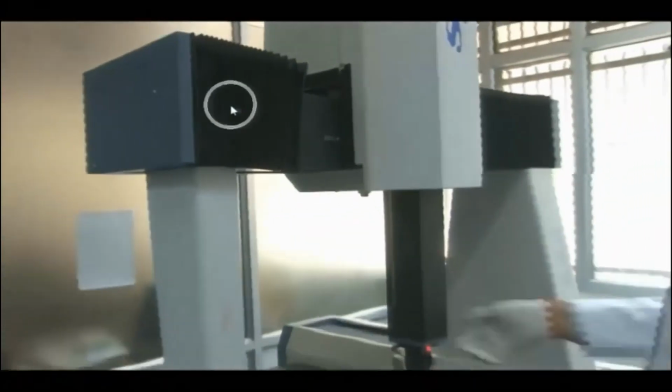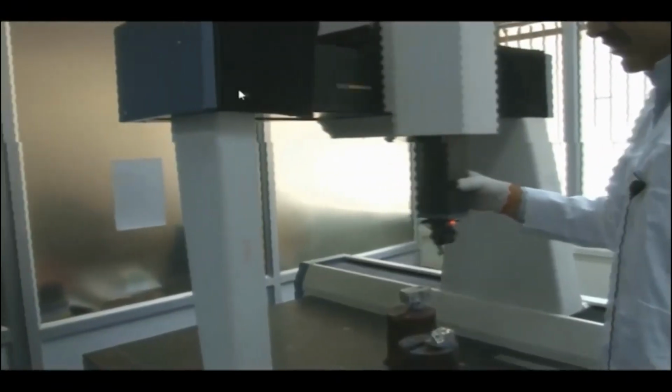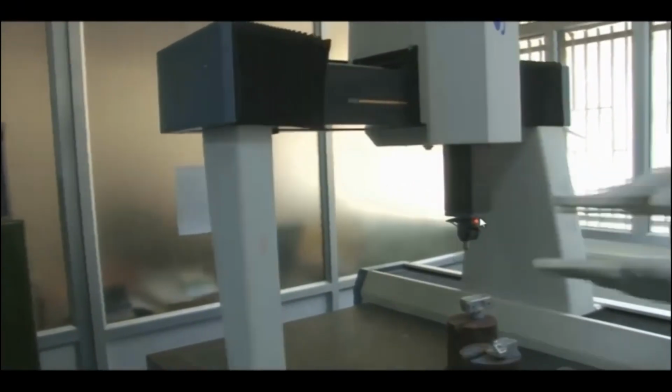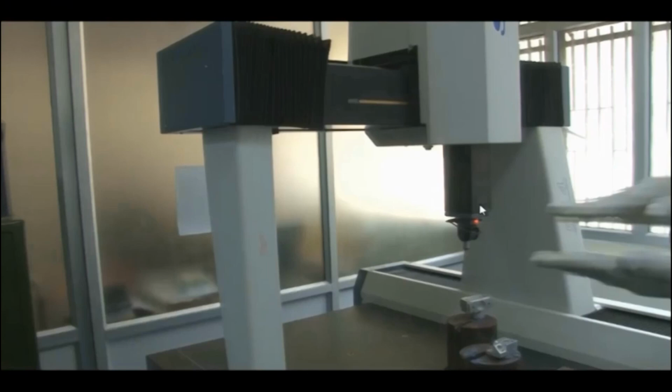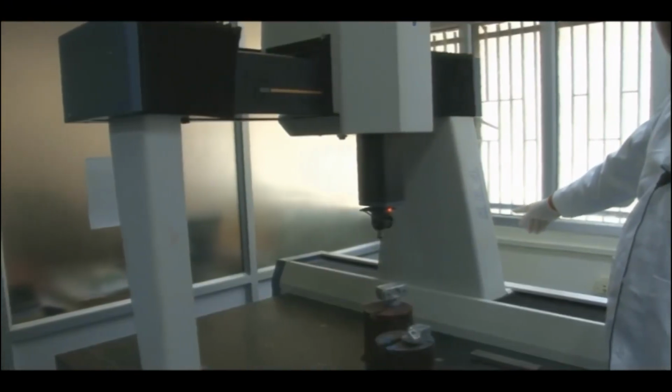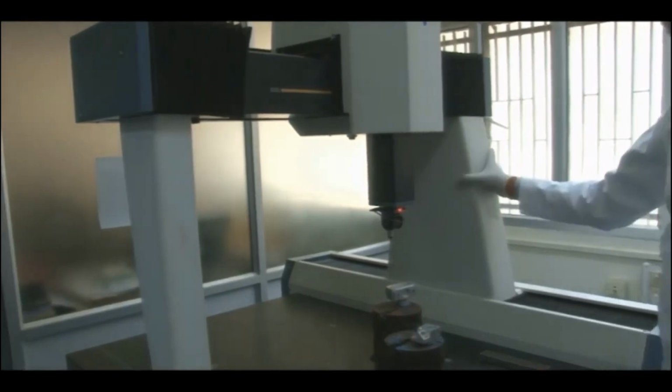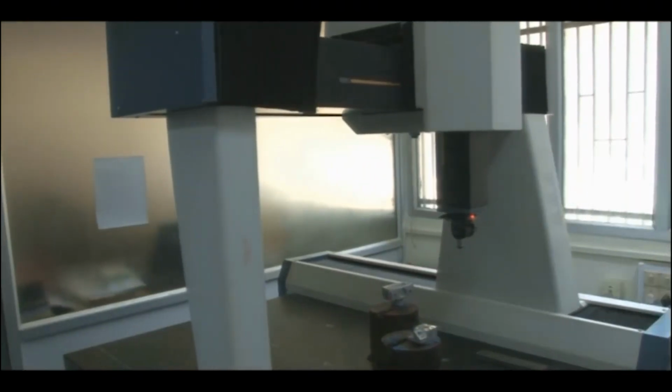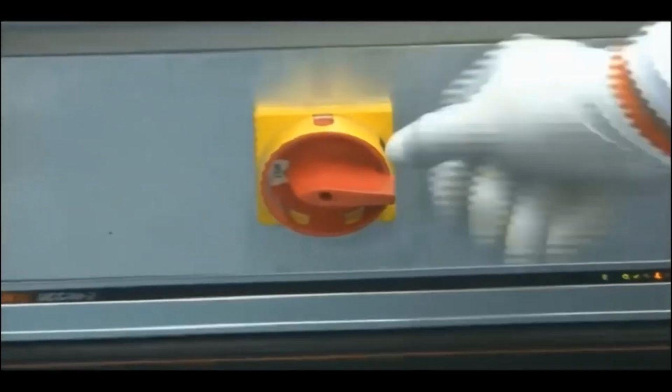This bellow helps to save the machine from dust and keep it secure. It can move freely, so it can compress and produce a spring motion due to air flow. With air flowing between the two surfaces, it can compress and produce the spring motion so that it can move from one side to the other. There are 6 bearings on this side, so side to side movement is possible, and a micro film flows due to completely dry air.